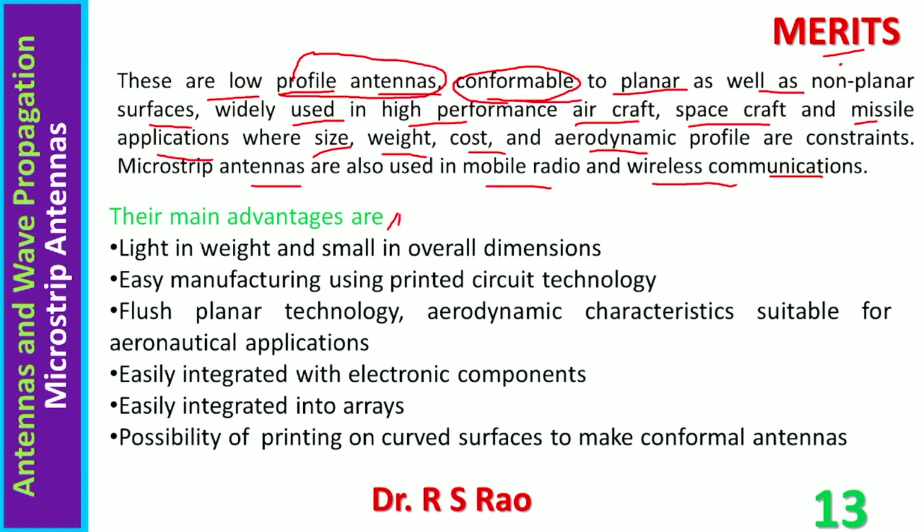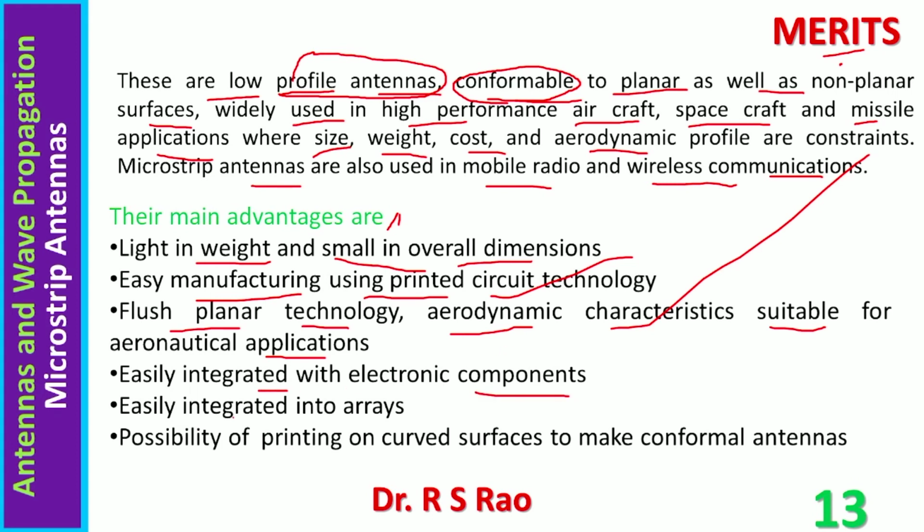Main advantages are light weight and small overall dimensions, easy manufacturing using printed circuit technology, flush planar technology, aerodynamic characteristics suitable for aeronautical applications. They can be easily integrated with electronic components and into arrays, with the possibility of printing on curved surfaces to make conformal antennas. These are all advantages.